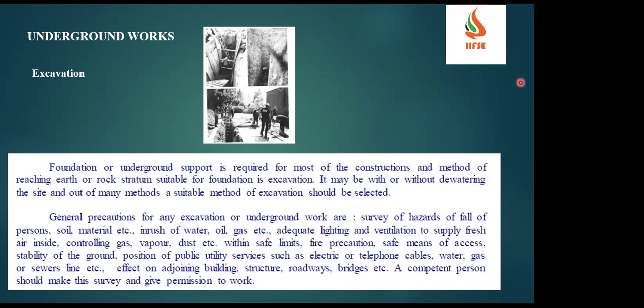So before starting excavation, we have to understand what kind of services are passing through the area where you are planning to excavate. We have to check for that. Once any specific utility is found going through, we have to isolate that specific service. Then we have